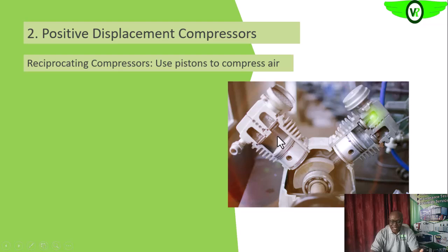When it gets to the bottom dead center, it will start returning. As it's returning, it will be reducing the effective volume of this cylinder, and that in effect will cause the compression of the gas molecules and increase its pressure. The pressure will be increasing up to a stage, and then the discharge valve will open up, and the gas will come out with that increased pressure as compressed gas.